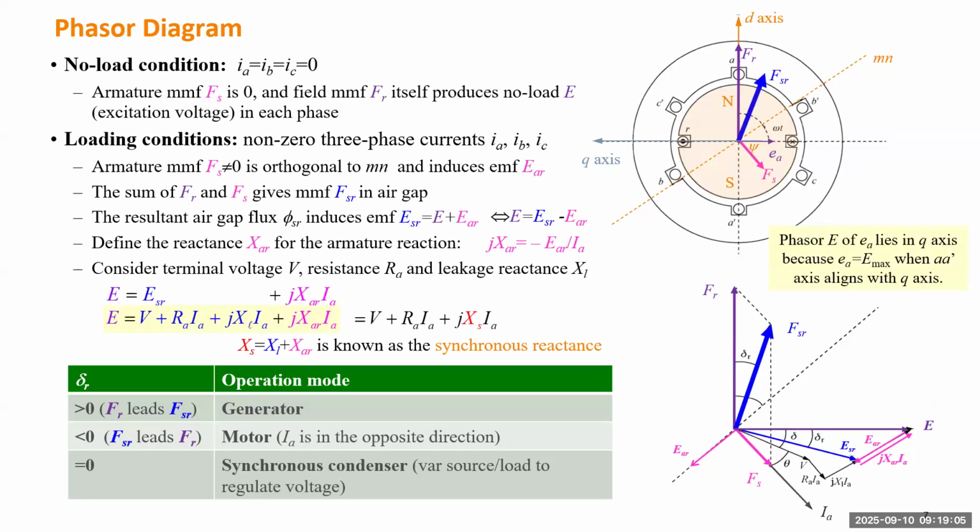Okay, so for a round rotor generator, although the rotor has the D axis and the Q axis, D means the N direction, and Q is 90 degrees leading the direction of N, which is the flux direction. But when the rotor revolves inside of the stator, if you look at the rotor from the stator, there's really no difference because the air gap is the same everywhere.